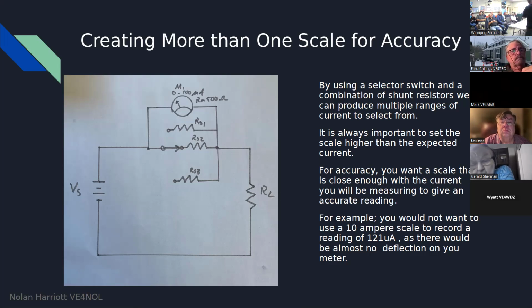But again, realize that your meter is part of that circuit. So your shunt resistor does actually look like a load resistor in that circuit.